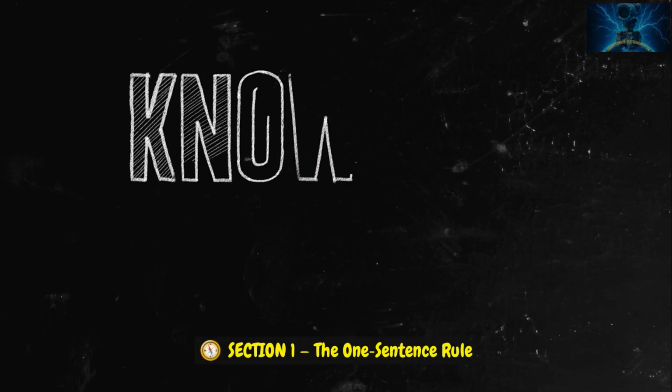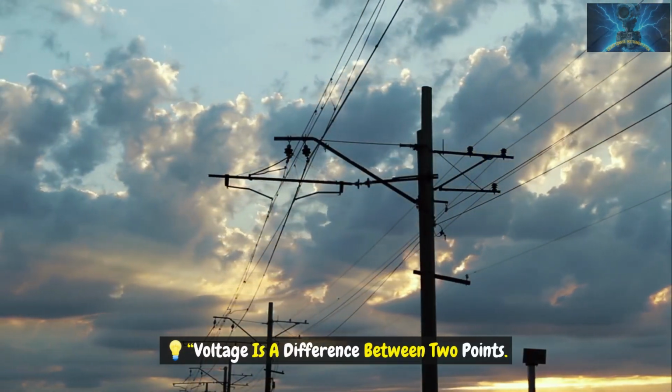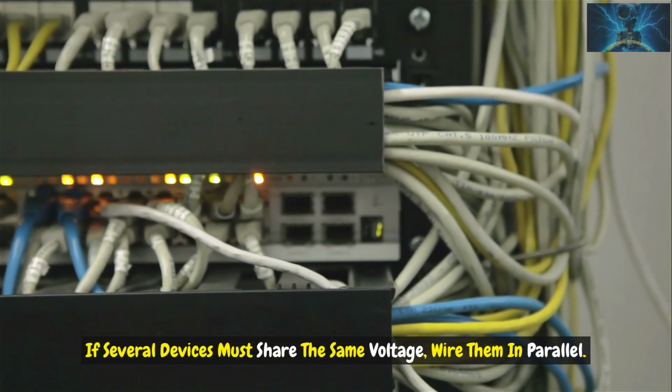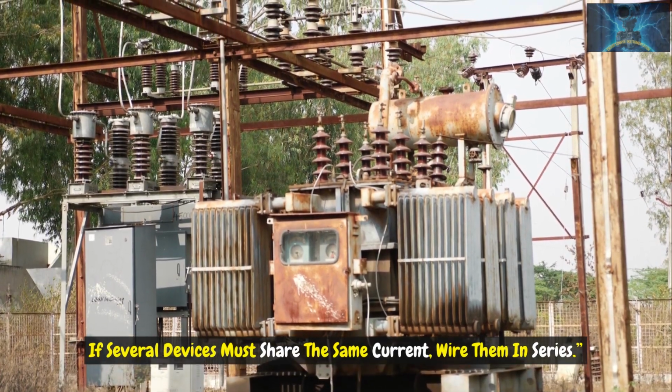Section 1. The one-sentence rule. Voltage is a difference between 2 points. If several devices must share the same voltage, wire them in parallel. If several devices must share the same current, wire them in series.